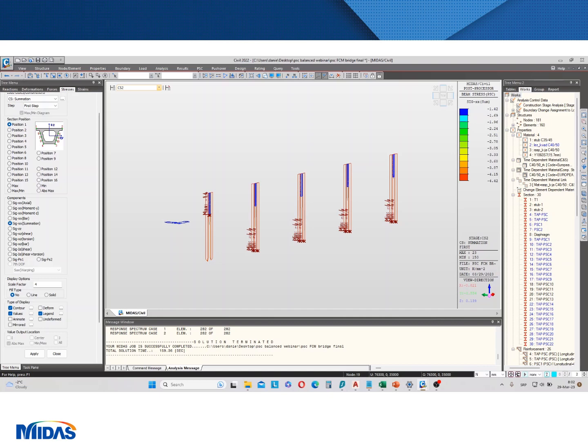Starting from construction stage 2, as you remember maybe, I have mentioned that internally every construction stage has its own steps. Here you can see how this actually works practically. If we choose user step 1 and we apply it, you will see that some little changes in stress values have happened.